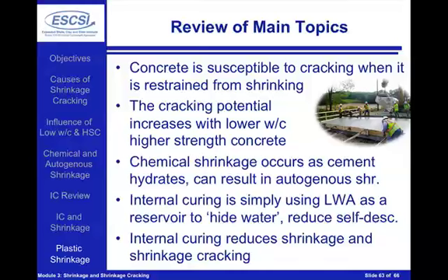The main reason for this is because we're going to have more autogenous shrinkage taking place in these cases. We frequently see a rise in the cementitious content, which can be a rise in paste, and we can also see many times the pore structure being modified to have a smaller particle size distribution. And this really leads to that rise in autogenous shrinkage.